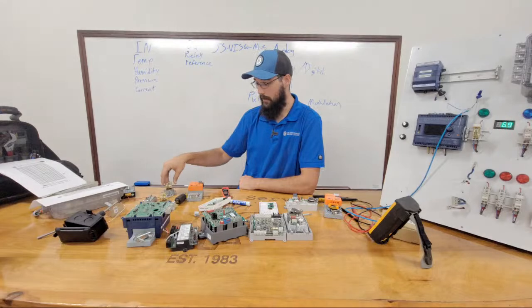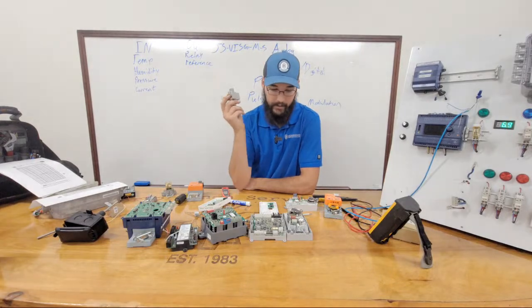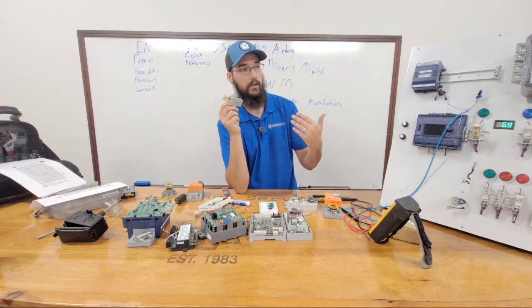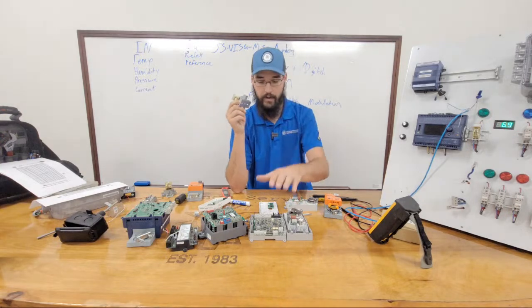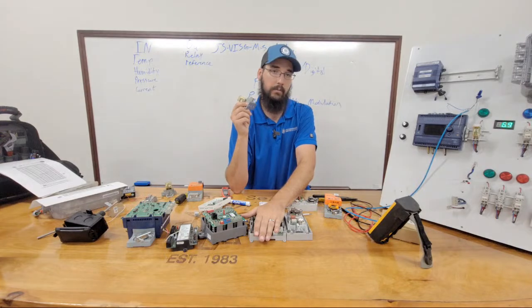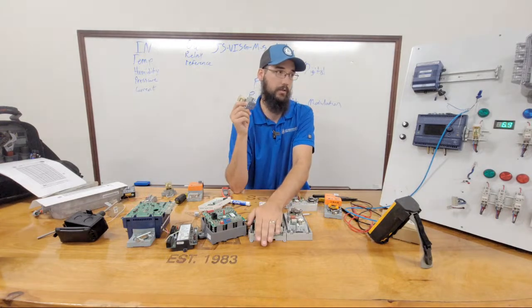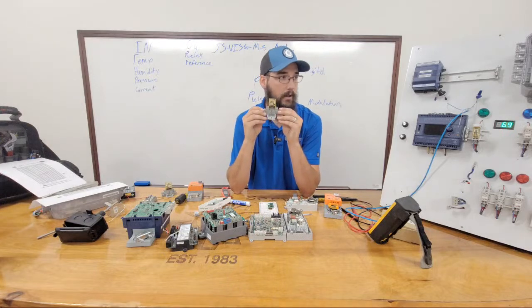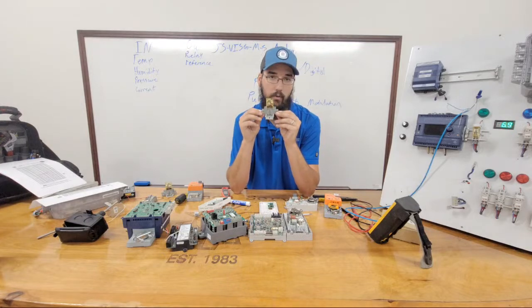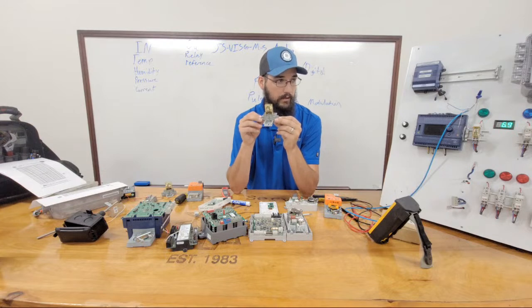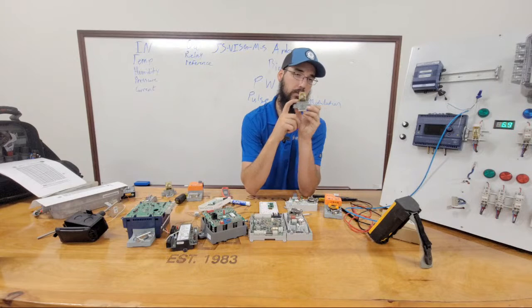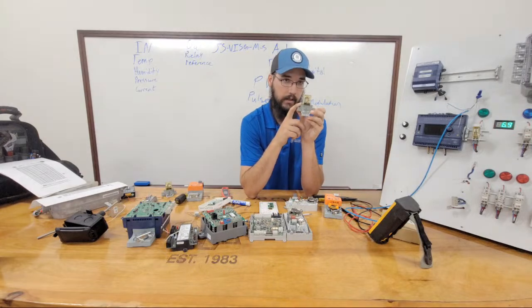So at that point, my recommendation is use this to control. You don't want to hook your contactor coil straight to those triacs, because they're not going to appreciate that, because then you're going to start burning controllers out. But at the same time, I don't want to run my heater or my fan through this contact either. So I'm going to feed from the controller to my coil on the ISO relay.